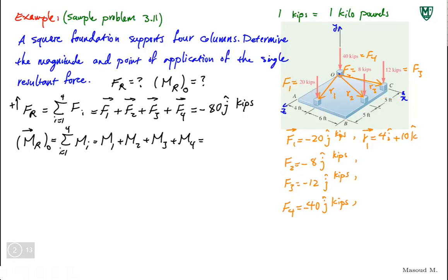All right, R2, position vector 2, the amount that I'm going to move the force F2 to take it from wherever it is to point O. That will be 10i, X is 10 in this direction, and Y is 5, or better to say Z is 5, because they're all in the XZ plane. Y for all of them is 0. So plus 5k. If you don't see it, let me know.